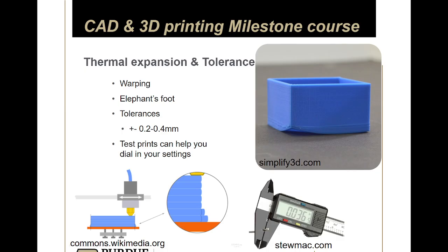But one of the ways you can mitigate or eliminate this being an issue, even if it is a thing on your 3D printer, is again adding a chamfer, right? So if you add a chamfer on this bottom face, you cut it here at that 45-degree angle, and then if there's any elephant's foot, it'll push outwards, but it still likely will be beneath this vertical face here, right? So if you add chamfers to the bottom face, you eliminate the issues that come with elephant's foot. So that's something to keep in mind. I don't know if it was a good example.